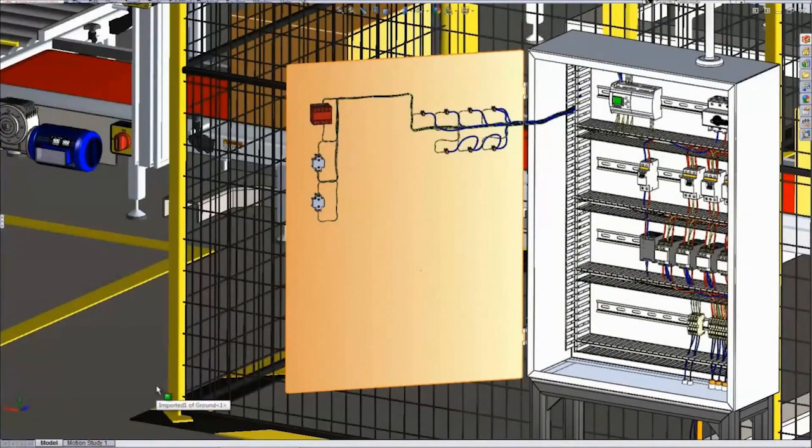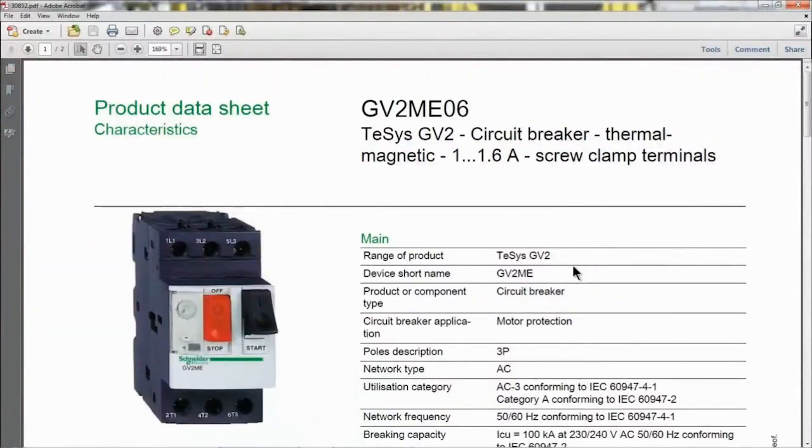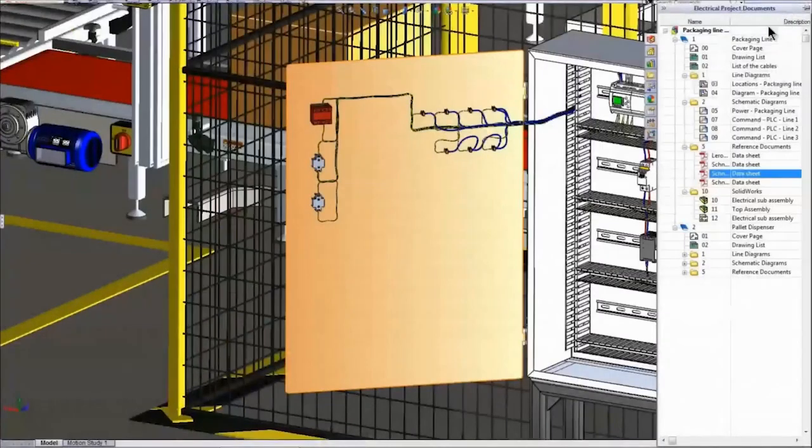We want to create our wires and cable routes to this cabinet from the schematic and get those lengths, as John said earlier. So we're going to first notice that on the right, this is a project. And in a project, you can have multiple document types like this one, the data sheet, which can explain that specific data sheet for that component.